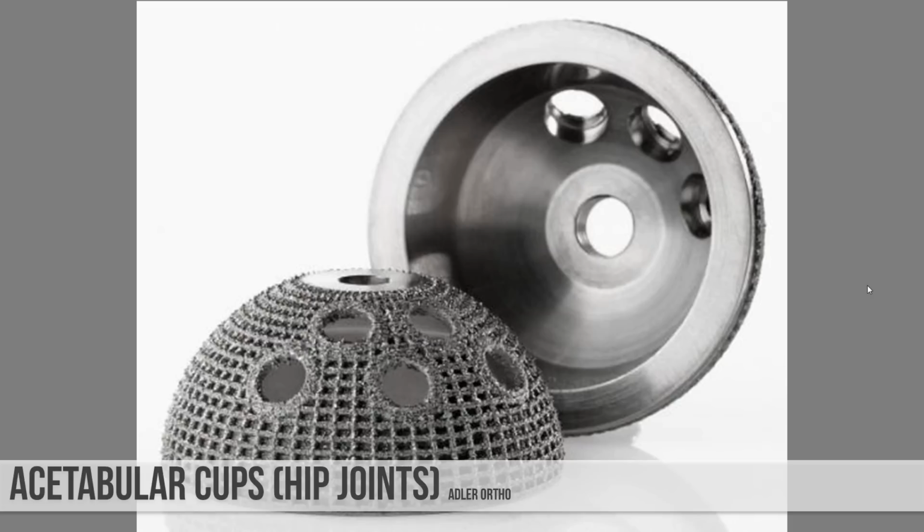All right, so acetabular cups, these are hip joint parts. These are kind of famous now for the biomedical application side examples. I call this a bone mesh that you see on the outside of that dome. I don't think that's the official term, but it helps promote osseointegration. So this is a cup that replaces the ball joint in your hips. That cup is inserted into the pelvis, and it eventually needs to integrate into the pelvis. All right, so you have these shapes that kind of promote bone to grow into the part. You can't create those shapes any other way. So osseointegration is a big deal here.